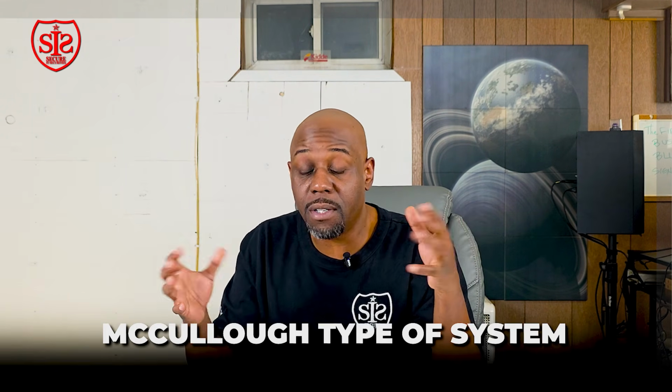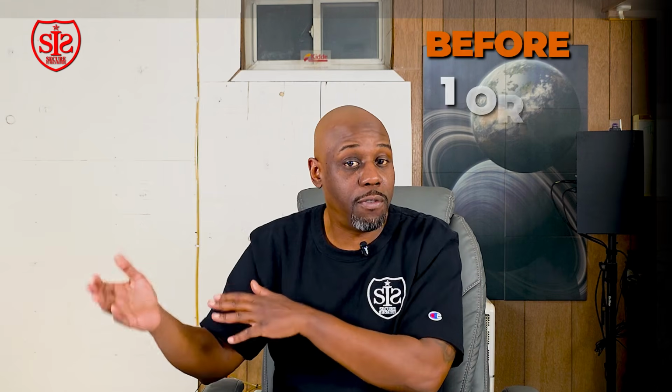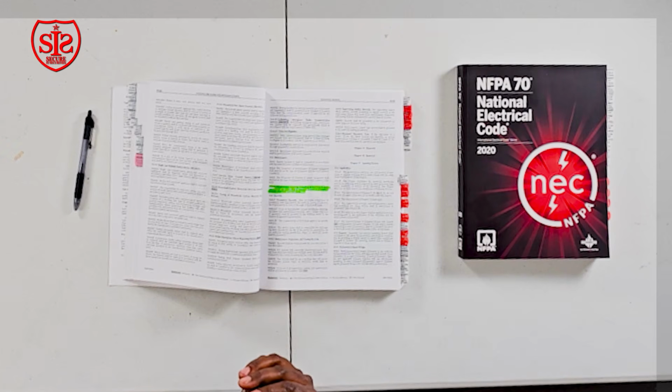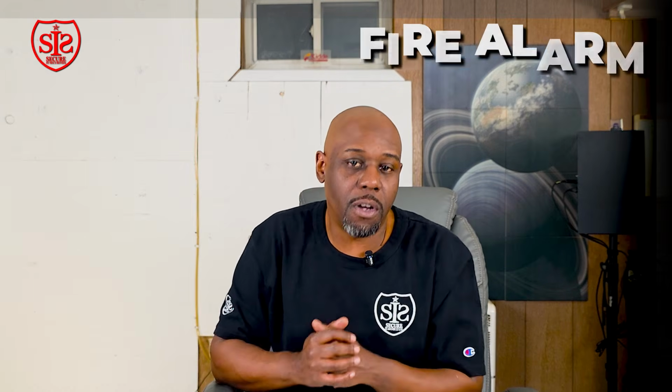So if you're still dealing with a coded type of system, more so the McCullough type of system, there may still be these old systems out there where a pull station will go into alarm and that pull station will have to be physically rewound. That way, if that device needs to be used again, it can sound the alarm in the rounds that it's supposed to sound, whether it be 4, 1, or 4. You may see this out there, you may not. This may be a test question, this may not be, but there's still information you need to know as a fire alarm technician.